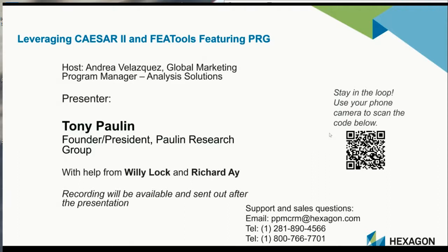Okay. Shoe lateral and axial capacities were supplied by PTP or determined by PRG? Determined by PRG, actually determined by a NozzlePro finite element analysis. All of the pipe shoes for all of the wall thicknesses for all of the diameters, Willie and his group ran, and those are all stored in the PTP library.